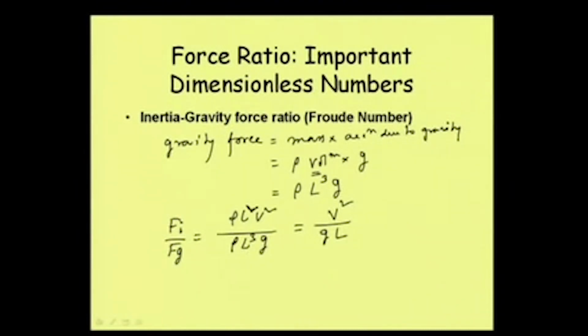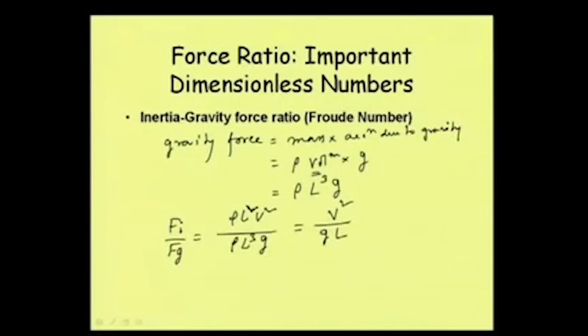Again, that is why we call this L the characteristic length, and for different situations this characteristic length differs. In the Reynolds number, we remember that when we were discussing pipe flow our length was diameter. When we were discussing, say, open channel flow, we took this length dimension as hydraulic depth. So, for different quantities, when we study boundary layer, then for that Reynolds number we again take the length dimension as different. So, that is why we are writing this dimensionally.